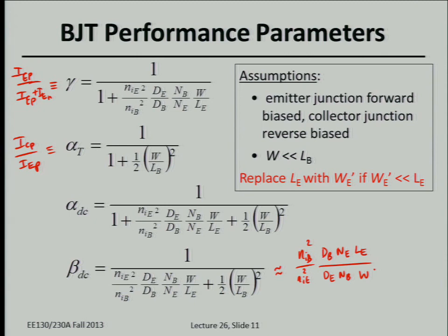Okay, so last time, remember I mentioned we usually would like to have high gain, and to do that, we want to make the emitter doped more heavily than the base. So this is consistent with that. And also, we would like to have the base width be relatively short. But remember, if the emitter is doped much more heavily, like degenerately, then the emitter can have some band gap narrowing. So Ni squared can actually go up, and that's counterproductive for enhancing the current gain.